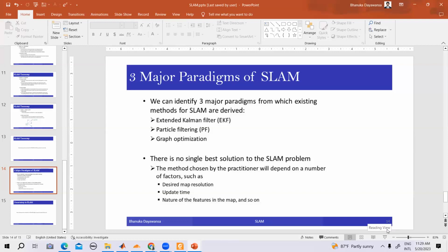It's not going to be feasible for you to go with something like a holonomic or omni-wheel type robot, right? So you might have to go with something like differential drive. But say you want to climb stairs and all, in that case, you will have to go with a robot that has tracks, right? You can't use a differential drive robot to climb steps.